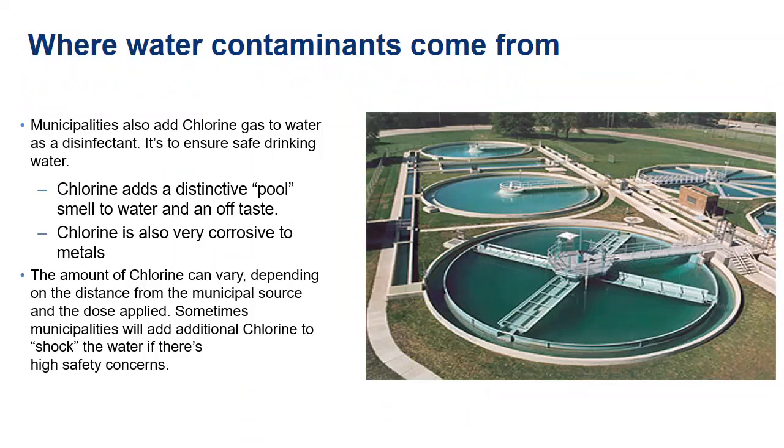Not failure. The filter's doing its job. It's just the chemical that was introduced by the water treatment plant makes that filtration more effective and therefore shortens its life. But this helps improve dirt load. Why are we focusing so much on dirt load at municipal water treatment plants? It's because bacteria and viruses can hide behind the dirt. We remove the dirt, treat the bacteria, sanitize it, get it out into the marketplace. That's the real goal of municipal water treatment.